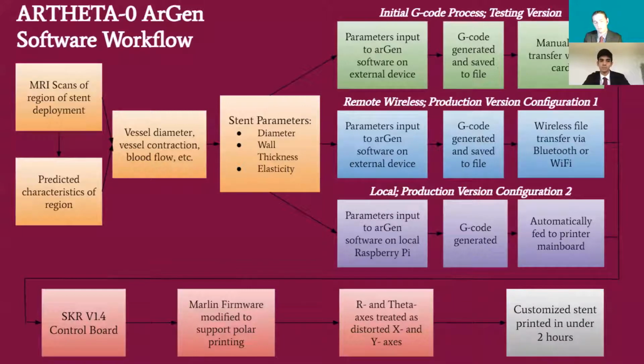One thing I will note is that for the firmware, instead of developing it from scratch, we've actually taken a modified version of Marlin, which is open source and very popular within the field. And then another thing is the question of how we are actually transferring that G-code to the printer firmware, to the printer mainboard. And we're doing this in one of 3 ways based off the printer's make and model.